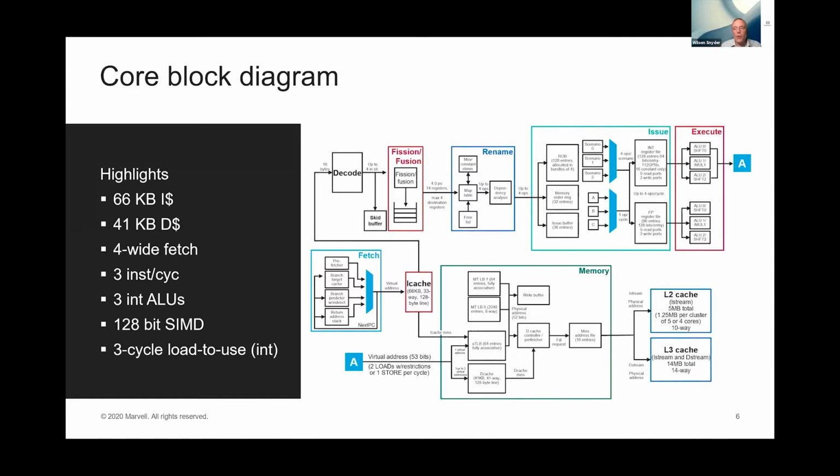Also in our execution units, we have full floating point units, and we also have a SIMD unit, 128-bit SIMD, which lets us do things like deduplication or, for example, some compression in hardware or RAID or any of those in the SIMD unit. As far as we're aware, we're the only people left with a 3-cycle load to use on the D cache. We get that by having our custom design team custom design the cache substructures. So most of the CPU is a typical PNR flow, but there are structures in it where we definitely took advantage of the very knowledgeable custom design in our group.